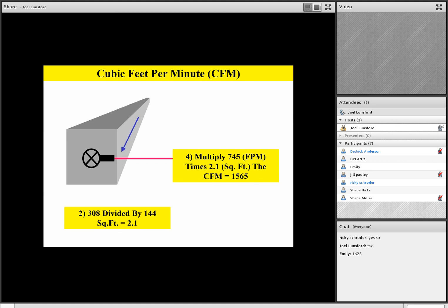So again, the tools that you'll need will either be a hot wire anemometer, also just called a hot wire velocity tool, or the rotating vane tool to find velocity. So from a point of explanation, the method that we're using for measuring airflow is called the velocity method.